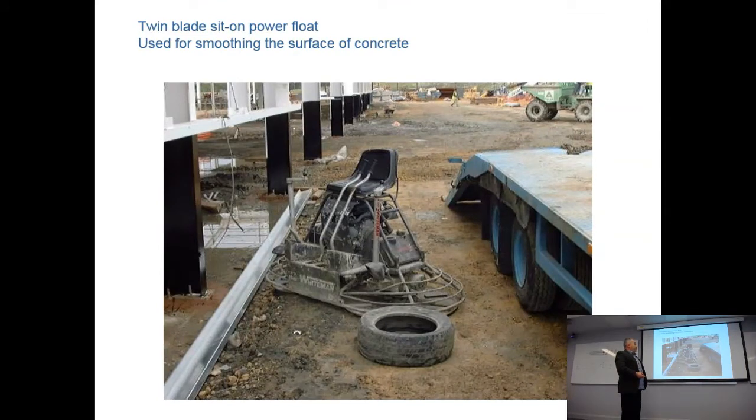I think you saw a video before of that's a power float. You've got your concrete, and you let it go off. And if you need a nice, flat, shiny surface, you can sit on that and drive around, and it polishes the top of the concrete.